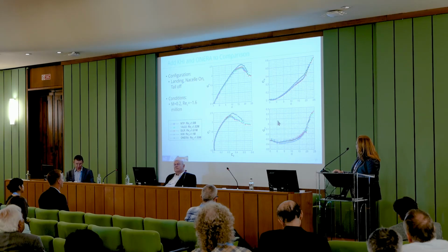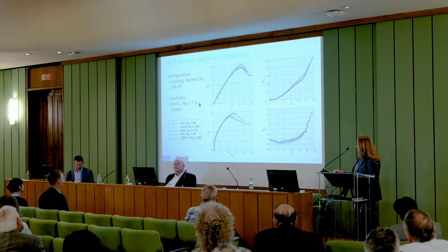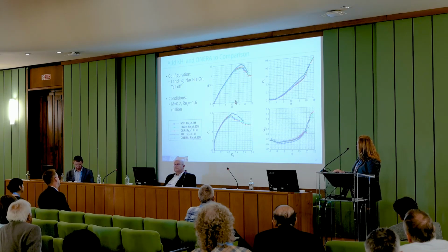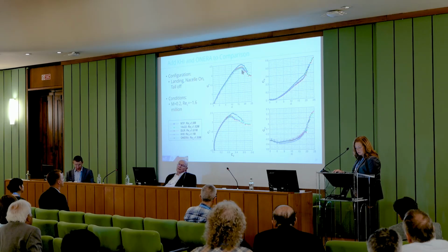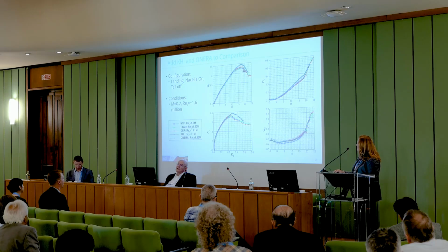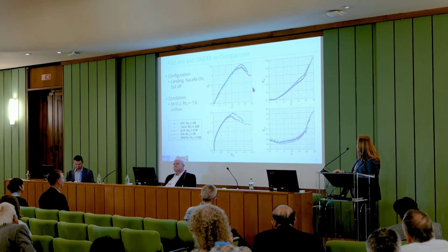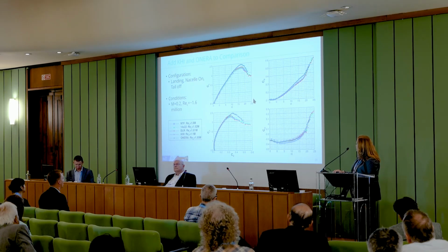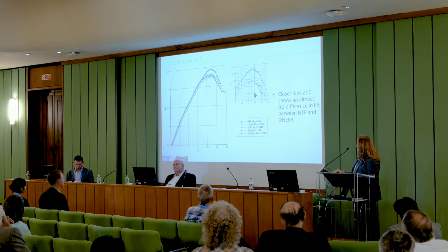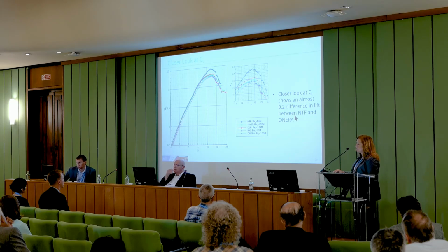Okay. And then, as you've already seen, we add the KHI data, which was another partner who had a test before the NTF test. And as you've heard about the AERODYNAMICS data, you see the KHI, which is the purple upside down triangles right here, mixed in with the blue right here. It compares really well to the NTF data, while, as you saw before, the AERODYNAMICS data, it's a lot higher lift than what we were predicting in NTF. So we looked into that a little bit closer, just to see what the actual difference looked like. And it is about a 0.2 difference in lift between NTF and AERODYNAMICS.